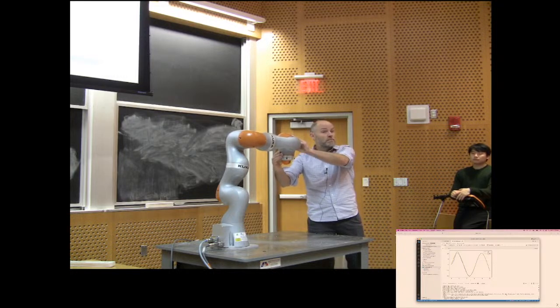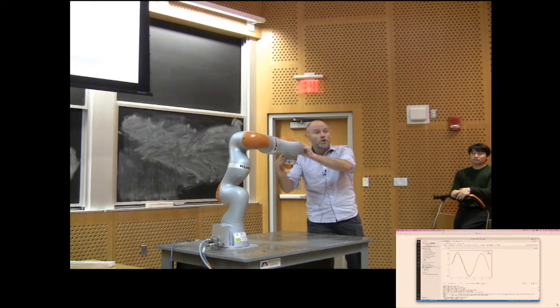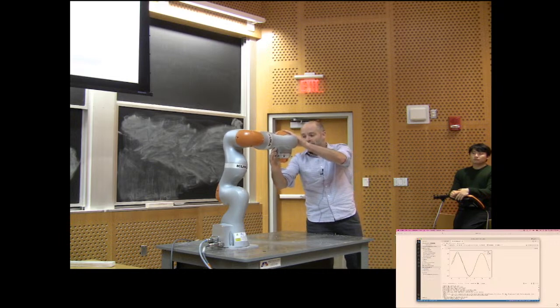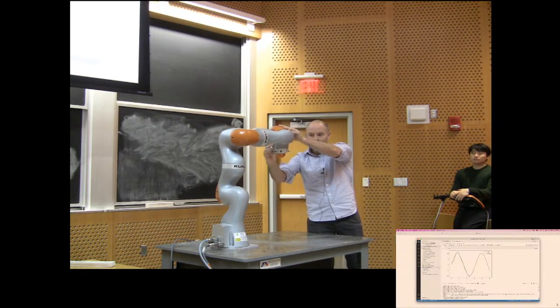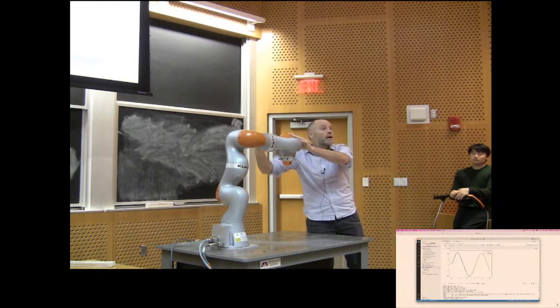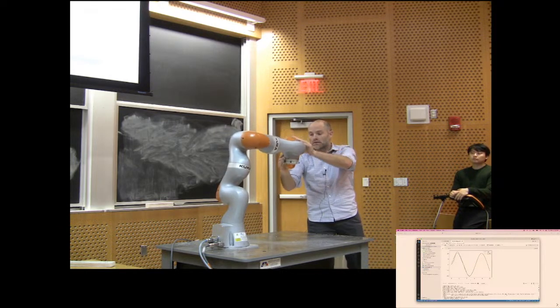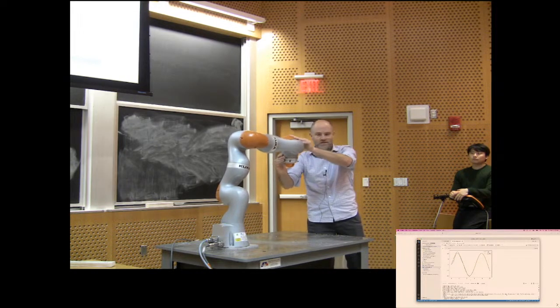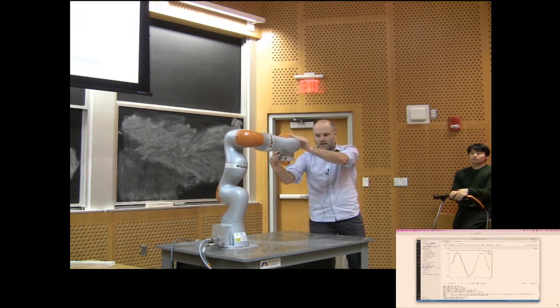It's going to let me move it, right? I can kind of move the robot around. It's going to resist. It's going to drive itself back to this nominal joint configuration. But it's in a complicated space, right? The response is a complicated function of the kinematics of the robot because every joint independently is looking like a spring. Okay? It's pretty beautiful, and it feels very nice and natural and smooth, which is a testament to the hardware, okay?